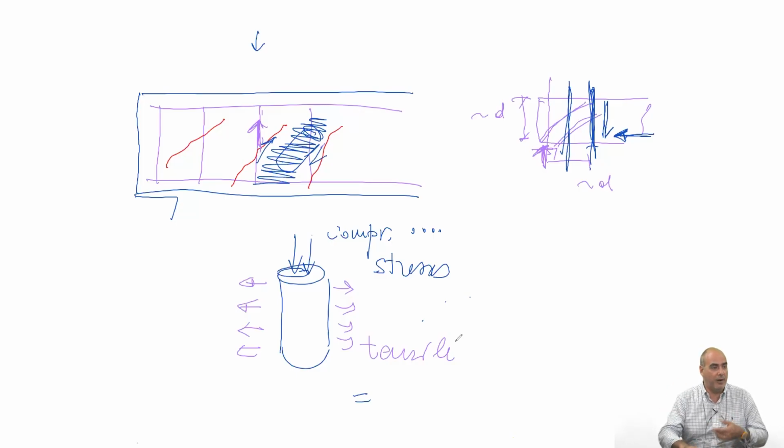And this comes from, Professor Aslan knows very well, studies which were done at University of Toronto and University of Houston. With the panel tester, they tested slab elements in concrete with reinforcement and so on under biaxial stress states to derive constitutive laws of concrete in one direction as a function of the state of stress and deformation in the other direction.